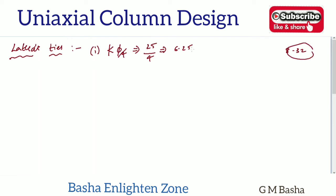So here 6.25, and the second condition is it should not be less than 6 mm. Out of these two, provide the higher value. So this is the higher value, 6.25, and the next bar size above 6.25 is 8 mm. Therefore we are providing the lateral tie of 8 mm. If you are choosing any other bar, like 8 bars of 32 or any other bar, take the longitudinal dia bar divided by 4.